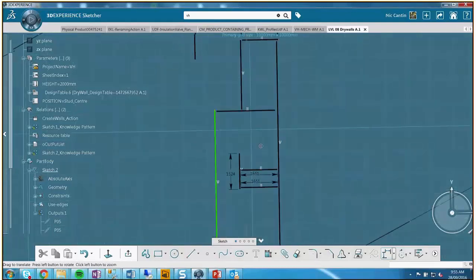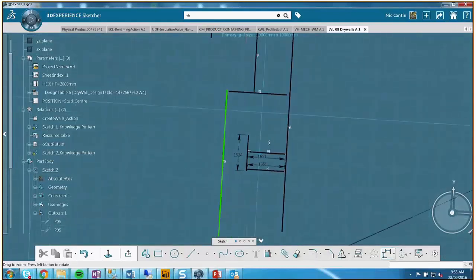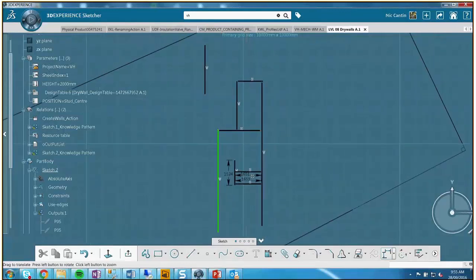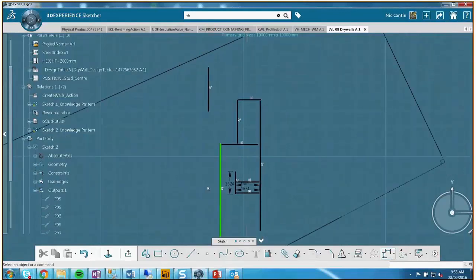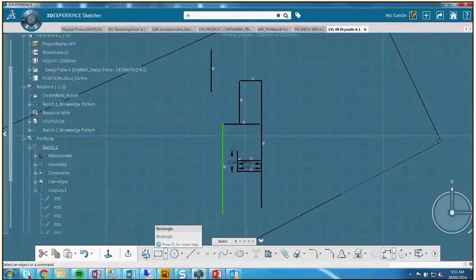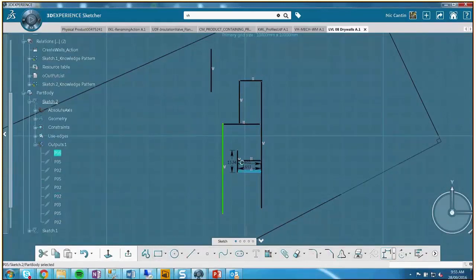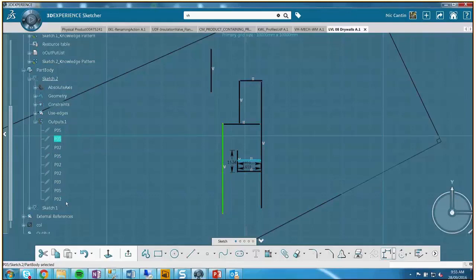You guys are probably better off in the sense that you get to constrain them right away and you don't have to read any drawings, you create the drawings. So essentially the same methodology though. We create the center lines and then output the lines, and then we rename each of the lines. You could use a script to do this as well, but we output each of the lines with a name for each wall type.